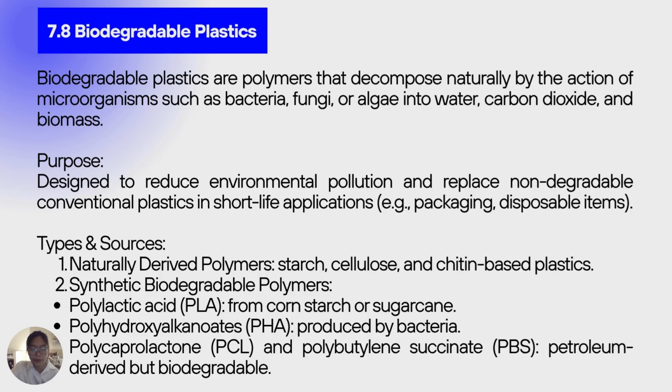Biodegradable plastics often have properties similar to conventional plastics, but with added environmental benefits. They are lightweight and flexible, with lower thermal resistance, so they are unsuitable for high temperature use. They are hydrophilic, which means water absorbing, which helps biodegradation but can limit long-term performance, and they can be composted, breaking down completely under the right conditions within months. However, in natural environments like oceans or landfills, where oxygen and moisture are limited, degradation is much slower. That's why biodegradable plastic should ideally be collected and processed in composting facilities, not thrown away with regular waste.